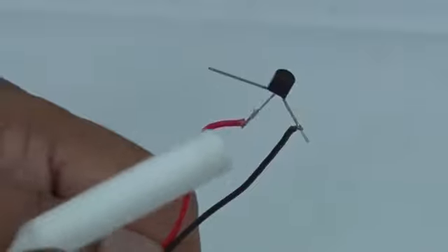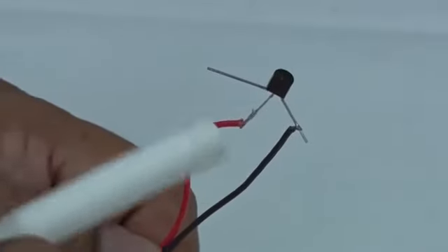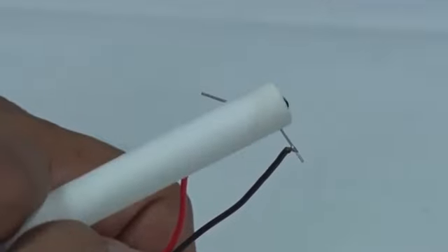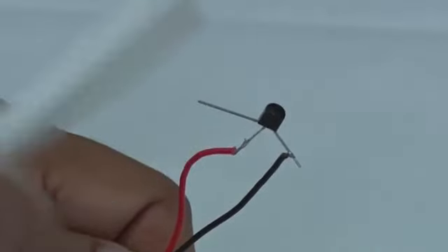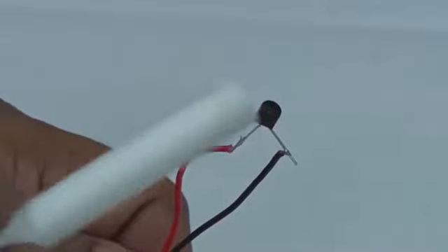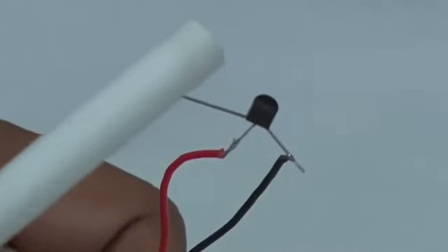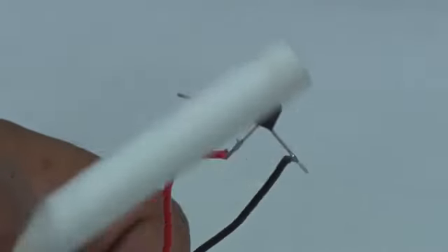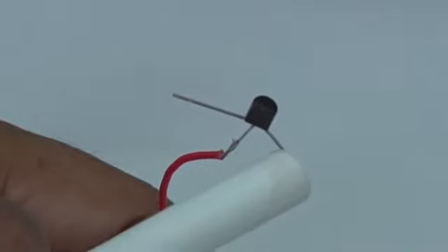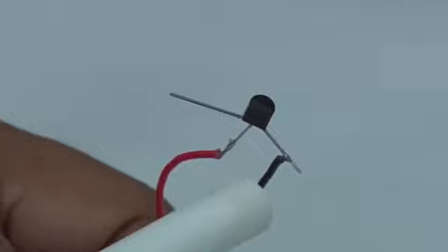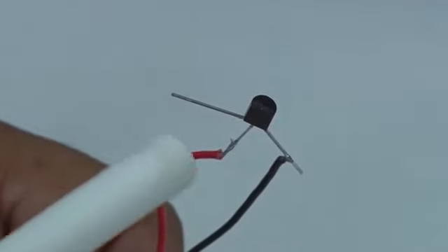This one is low power, used for small currents, and then you have other kinds of transistors where the casing is metallic, a full cylindrical type, and from the bottom there are 3 leads coming out. On the circular top there is a notch from which people find the first lead, second lead and third lead, and then the data sheet will say which is emitter, which is collector, and which is base.